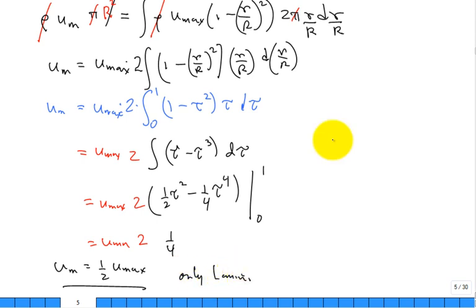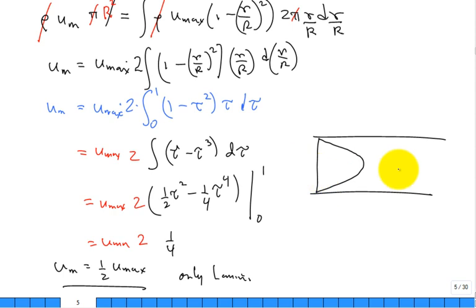Somebody says, hey, I have a pipe flow, and instead of being laminar where I have this nice quadratic shape, it's turbulent. What's the turbulent profile going to be? Steep, plug, steep, right? That's kind of the shape of it. It's pretty flat. Because it's turbulent, we have to talk about a time averaged velocity at each point radially, and it'll be like that. In this case, the maximum is over a broad range, not just at the center line.